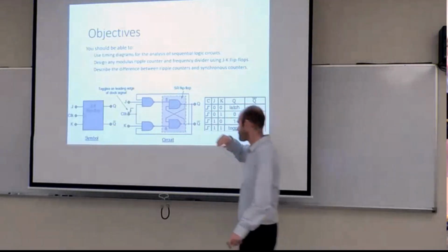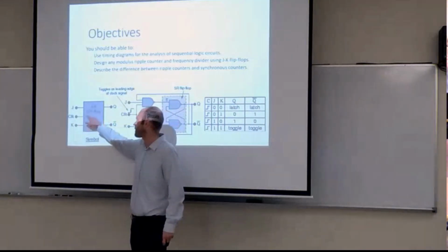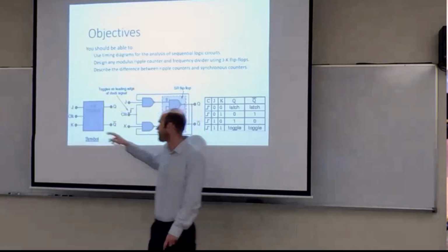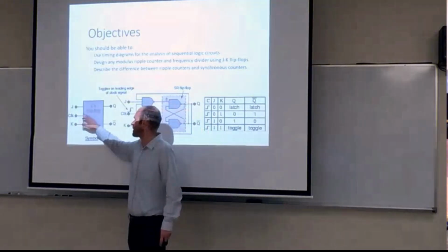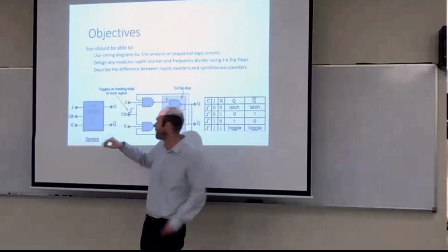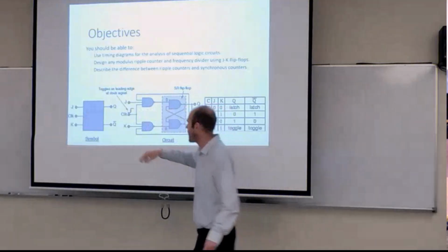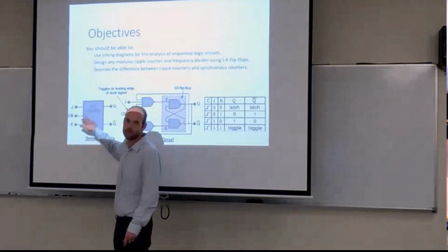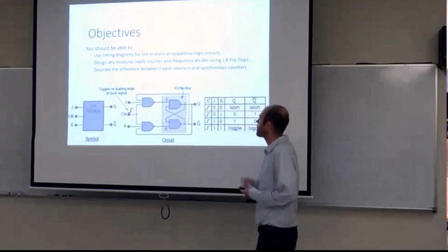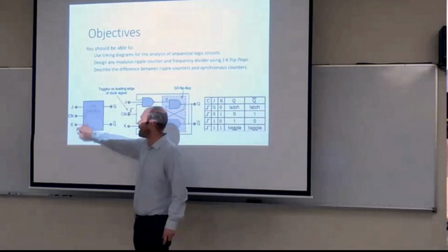Remember again that this is a clock edge driven device. The triangular icon here indicates an edge. If it's a rising edge, it looks like just a notch here. If it's a falling edge that's triggering the event, you have an inversion bubble on the top. We will see that edge notation in our iStudio as well when we're designing with our functional blocks. So just be aware that that's what we're talking about, clock edges.